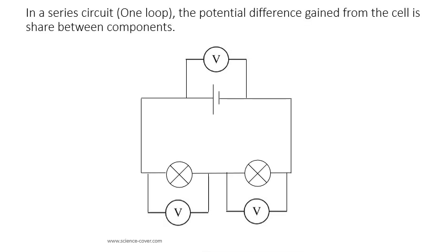In a series circuit with 2 bulbs, we take our 6 volts that is coming from the cell, and that 6 volts must be lost in the circuit. But now we have 2 bulbs. Assuming they are equal in resistance, it means that the voltage will be shared between the bulbs. So we lose 3 volts on each bulb.